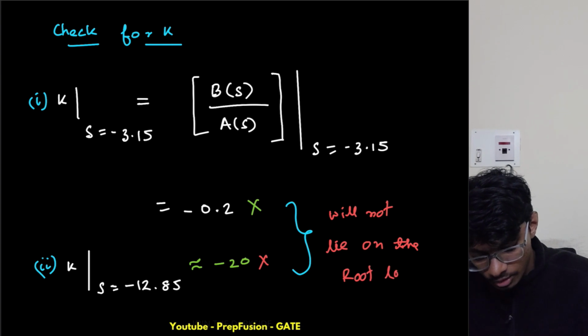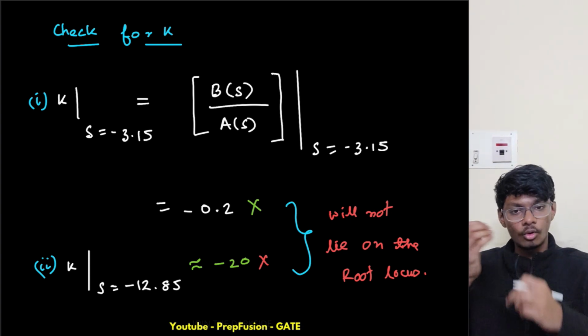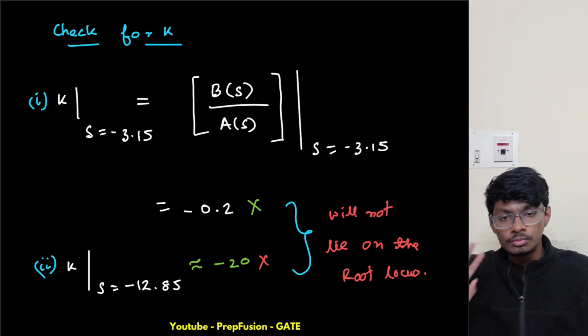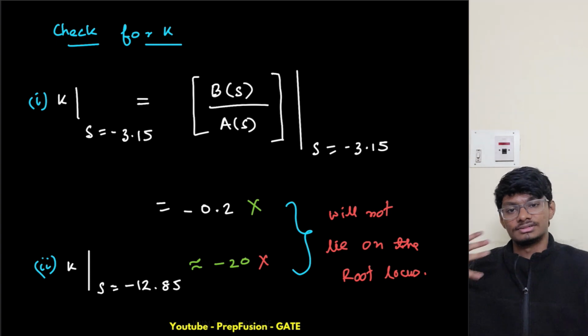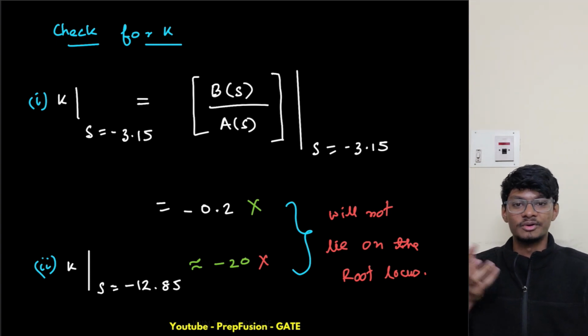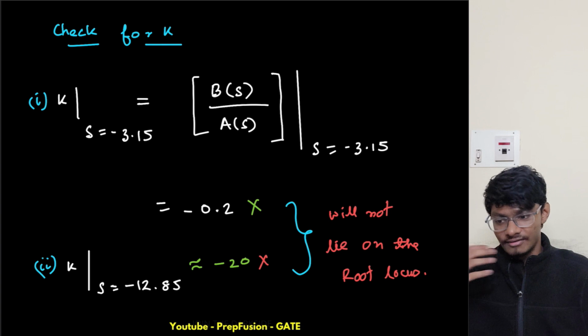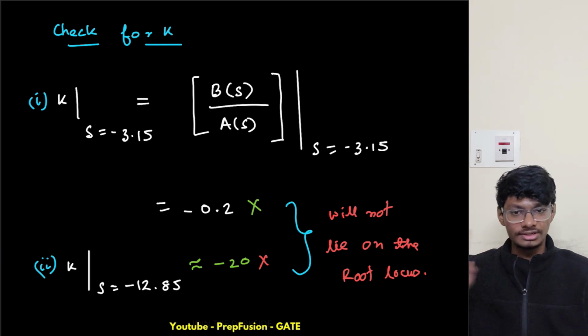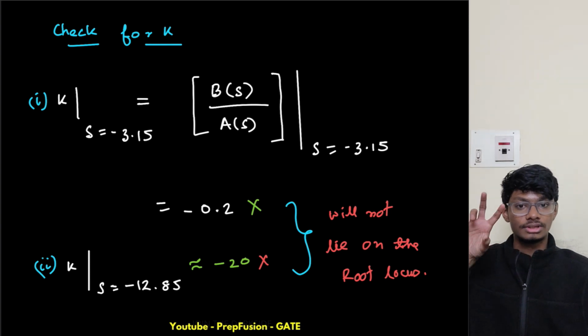One thing I hope you understood is that complementary root locus and root locus are not anything different. Here also we are plotting the trace of the path of the closed loop poles of the system. What has changed is that from negative feedback it has changed to positive feedback. So obviously a few rules will change, conditions will change, but it is just root locus only. Don't get scared that complementary root locus is something god-given and different, because during my preparation also I was scared of it. But after studying it a bit, I understood that it is nothing different. Just here I have positive feedback instead of negative feedback. That's why a few rules changed. Why? Because the angle condition changed.